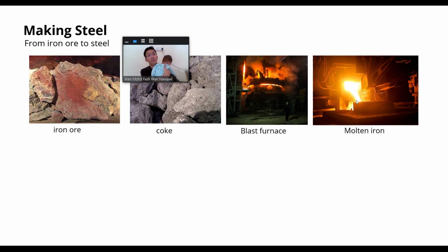That's the reason they can be melted. Where is the carbon coming from? The carbon comes from the coke. Because to make steel, you need to add carbon to iron. When you extract, you get iron only. There is no carbon, just some impurities, maybe trace carbon. But when you add iron and coke as a fuel, the carbon inside the coke will go into the iron.